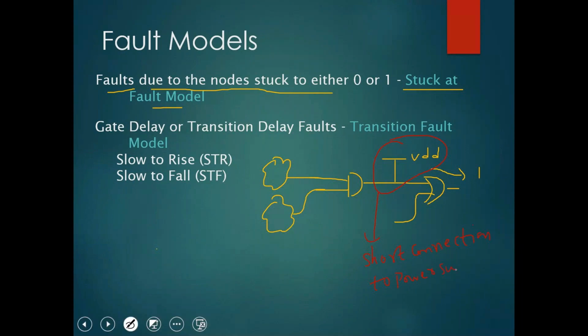and that is modifying your specification, because if it is always propagating a 1 at the output side, the right-hand side circuit will always see a value 1. You will never see the values coming from the B pin of the OR gate. The A pin of the OR gate also has very big logic, the AND gate inputs and all. Even that value is not seen, which means I can consider this as a defect. So this defect, logically, we call a stuck-at-one fault model.